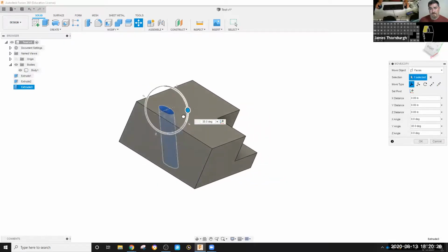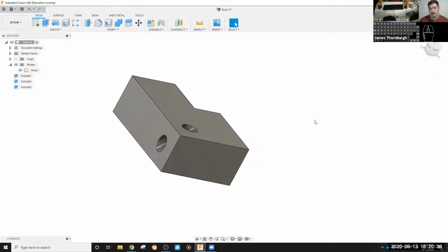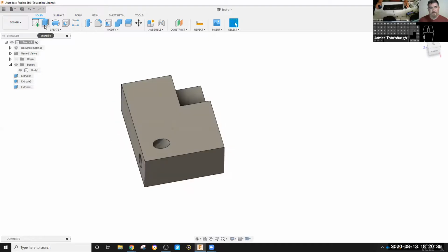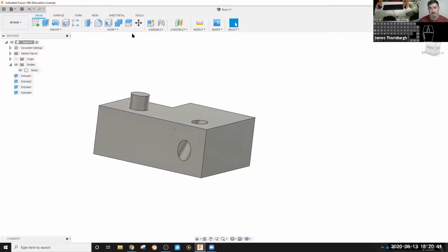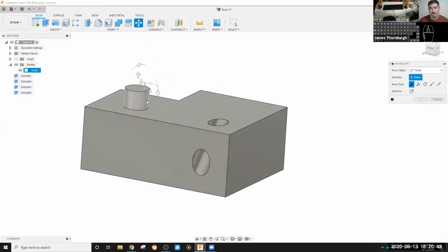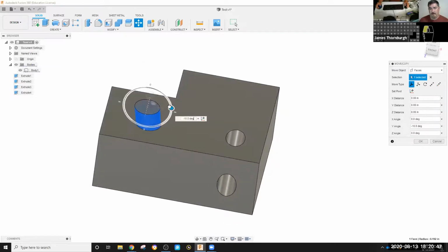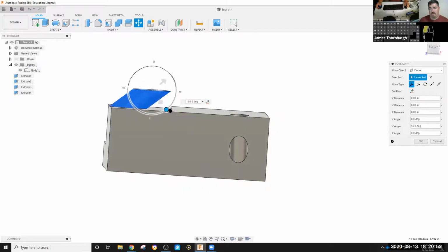I can tilt it. So I can actually tilt it up there, hit OK. Now it's going to the bottom. Now it's going to come out the side. If I had a cylinder that was sticking up, watch what happens now. If I click here and I pick the side face of it, and I tilt, the top of it stays kind of where it was. It's just adjusting for being an ellipse.